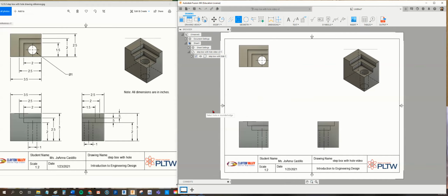Okay. So now let's dimension the rest of the drawings, the height, the width, and the length. Actually, let's do the easiest one like I have here. We go to dimensions. I'm going to click on the diameter and then hover over the edge of the circle, left click, and then go out, just like how I have the drawing here on the left.